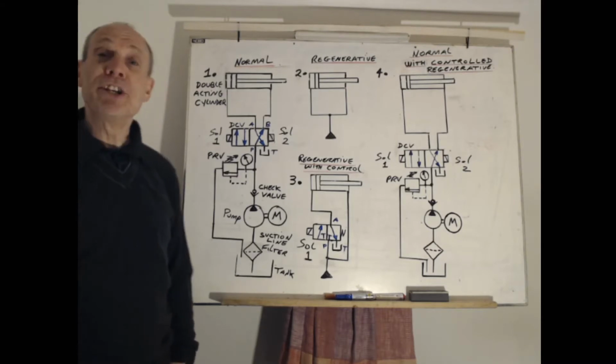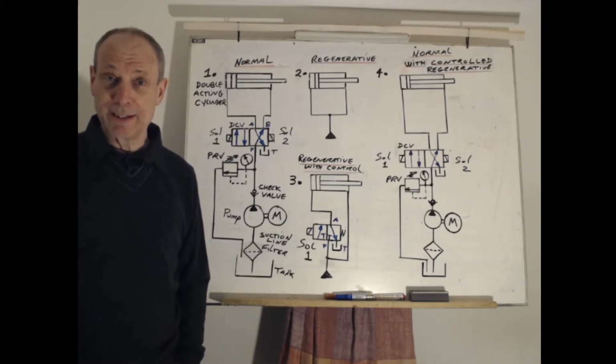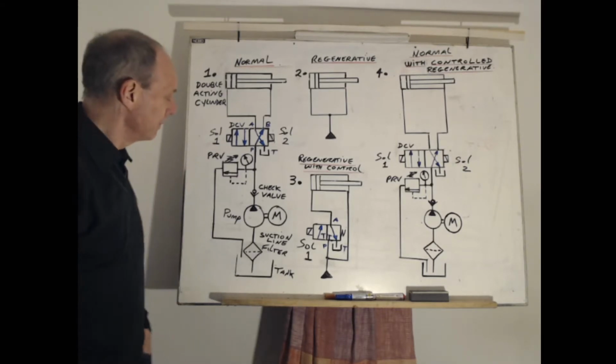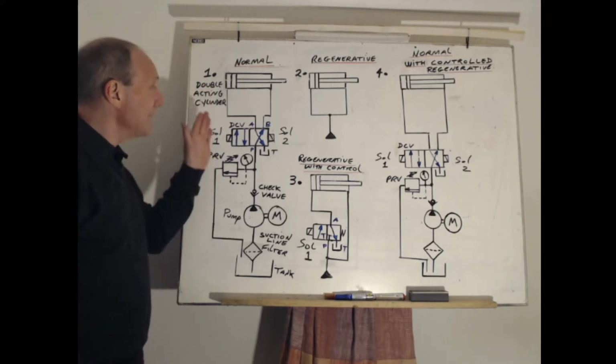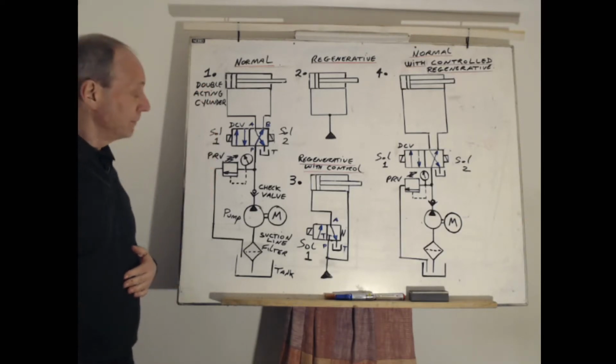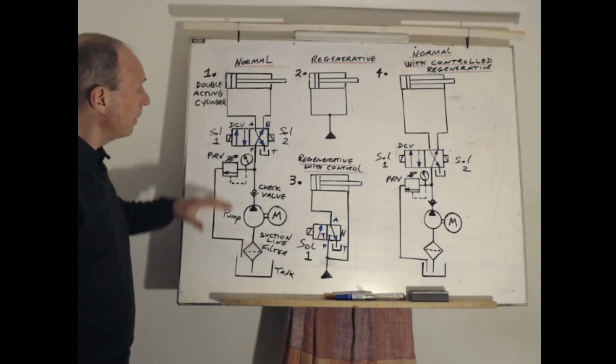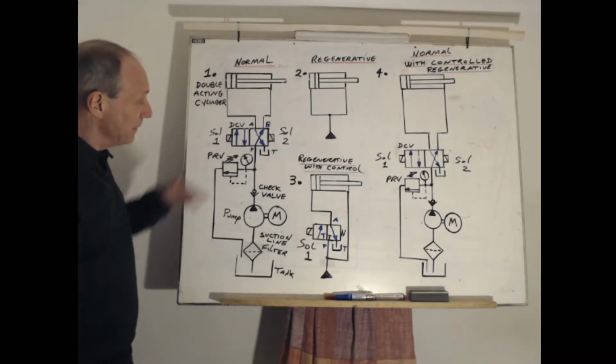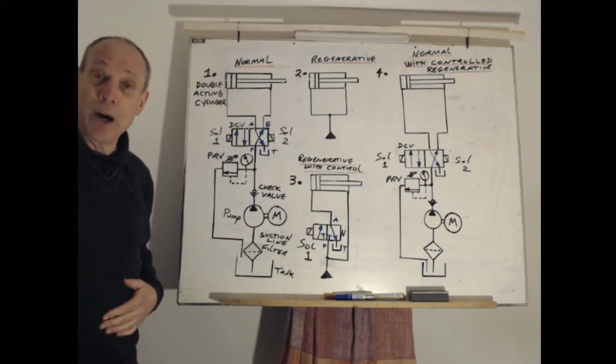We're going to look at the regenerative circuit in hydraulics. This is revision for you. On this circuit it's a normal operation. So we have some identifiable component parts. This lower part would be classed as the power pack.